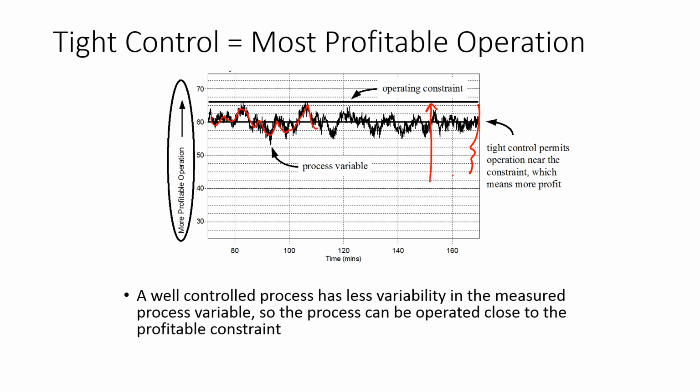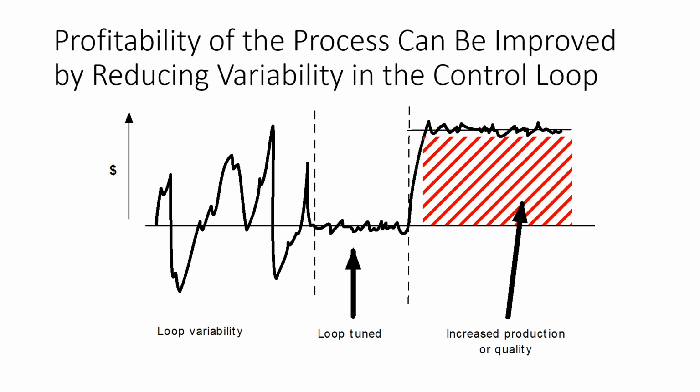And this difference between the former set point and the new set point often equates to a lot of economic incentive for process control. So if we are first operating in this regime where we have a lot of variability, we're able to control, and after a while, operations or others may be comfortable with moving the set point closer to an actual constraint.